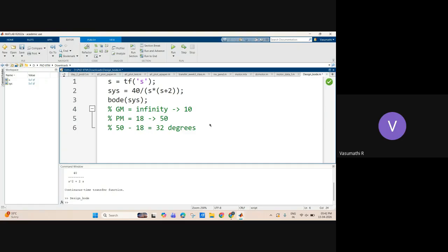But since it is a trial and error method, we won't do exactly that. We will have some 5 degrees compensation here and there. So I am going to consider 32 plus 5 to make it robust. I say that we need 38 degrees of increase. Okay, this is the base we have set up.